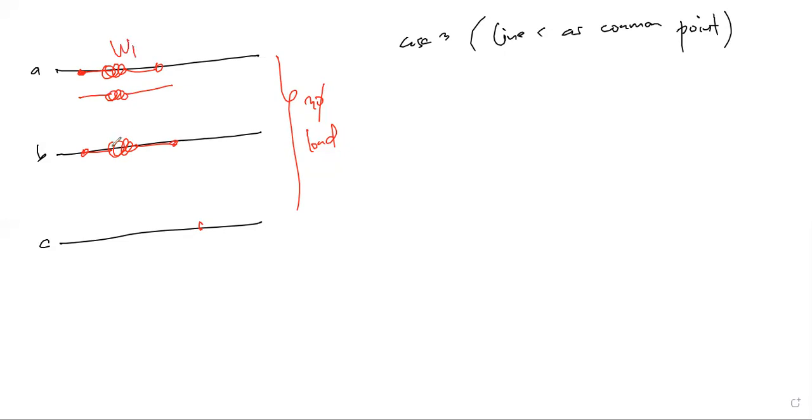So the potential coil of wattmeter 1, this is wattmeter 1, will be connected to A and the other one to C. For wattmeter 2, the left terminal is connected to B, and then the other terminal will be connected to C, like that. So then this would be wattmeter 2.